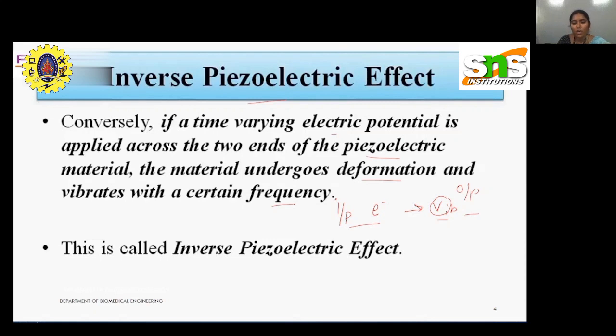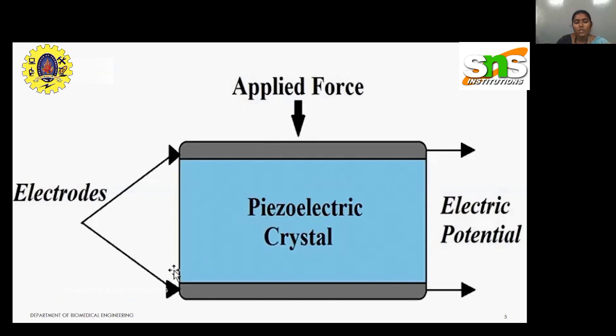This is based on application, we can use either of this. Okay, so let's see how it works. This is the generalized setup for a piezoelectric transducer. Inside the piezoelectric transducer, you have the unique crystal, that is the piezoelectric crystal. You can use either natural or synthetic piezoelectric crystal. Under no pressure, this piezoelectric crystal remains in its proper desired shape.